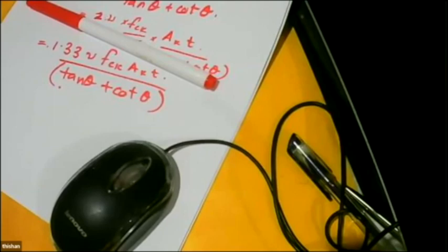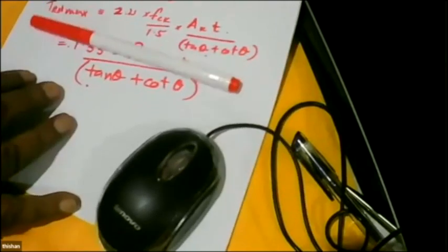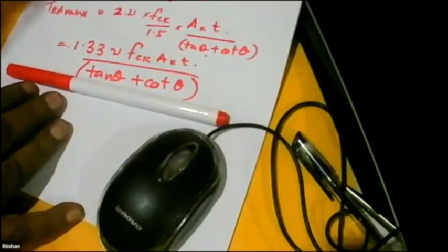Okay? Okay, sir. And the last question: how to provide for torsion in a cantilever beam? Torsion in a cantilever beam is not a problem at all, because it is a statically determinate system when it is a cantilever. So you straight away know the torsion. When you know the torsion, design the reinforcement in the normal way.